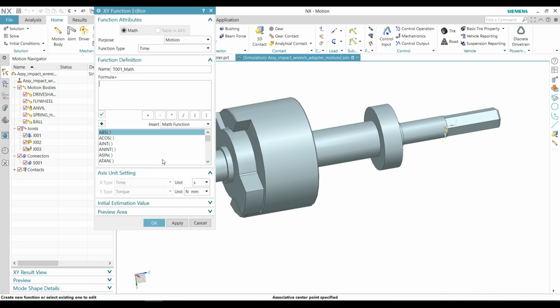In the second video, we derived an equation for the speed-dependent motor torque, which we will be using here. We will also be using an if statement here, because we don't want a torque higher than the stall torque if the drive shaft turns the opposite direction and the angular velocity becomes negative. For this statement, we also need the actual rotational speed of the drive shaft, so into the formula we insert a derived variable.